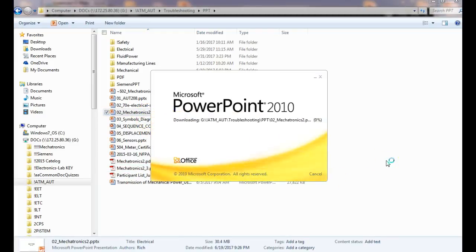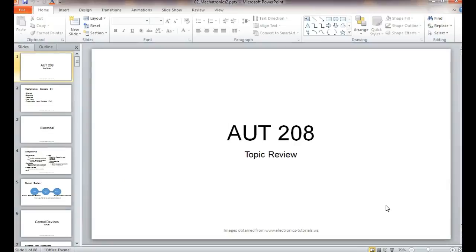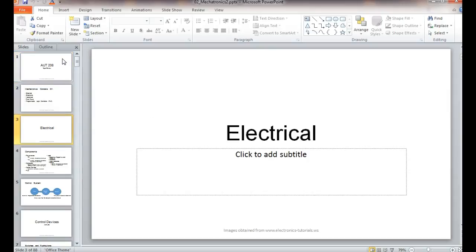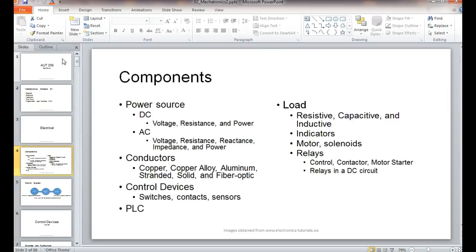So what problem do we have with single phase motors? What makes a motor turn? Magnetic field. But one of those magnetic fields has got to move. So in DC, of course, we create a shifted magnetic field with the commutator. We keep switching the polarity on the armature, which causes the motor to rotate. So what we're doing with a DC motor is shifting that field with a commutator.